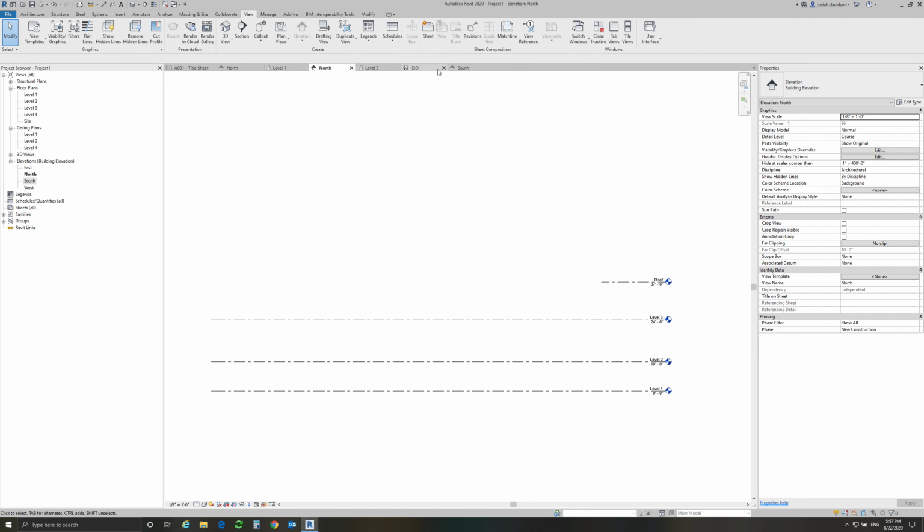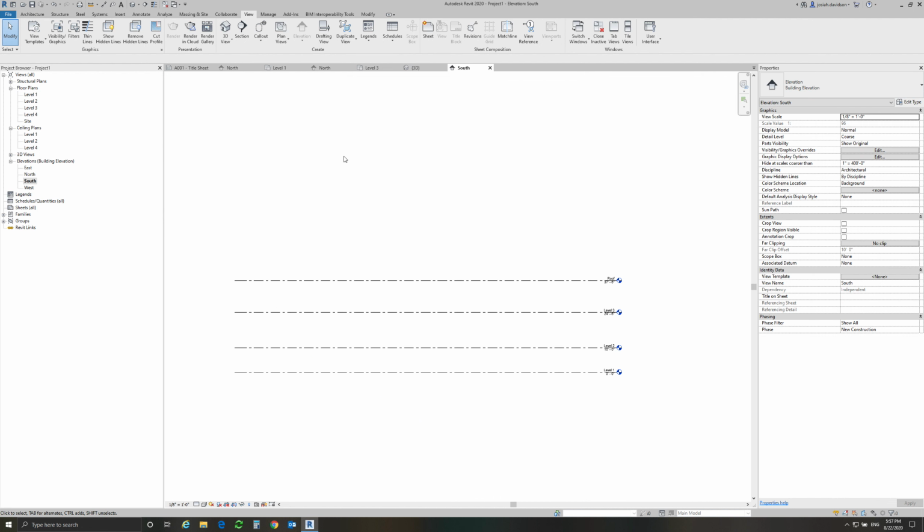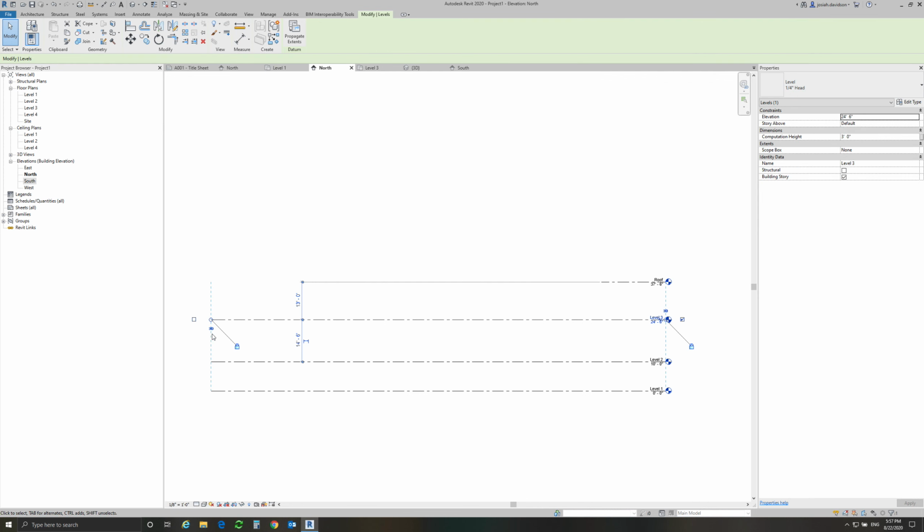And you'll notice when I go to the 3D view that it still remains full size in the south elevation. And so that's how you can adjust its appearance in a certain view rather than changing it across the board when it's in 3D. Notice when I grab these, I still have the option to toggle 3D on and off for this one, as well as remove the lock so they don't move all together. So that's kind of up to you.